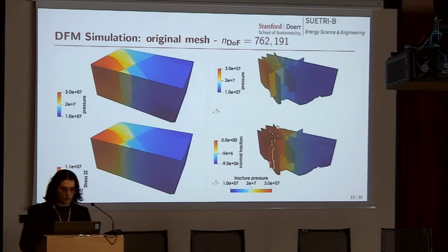So if you really look into the normal traction, and as I said, you look into the level set function, so whenever the pressure is exceeding 20 megapascals, the fracture will open. So therefore, the expected traction or normal traction is 0. So if you see the pressure is bounded between 30 here and somewhere 10 megapascal. So somewhere the pressure here is exceeding that limit, so you expect these fractures to be open. And as the level set moves to the, let's say, lower pressure zone, the fractures are closed.